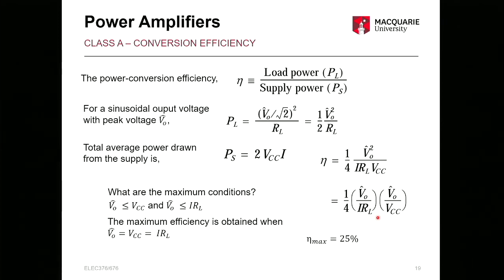You remember back to the waveforms, we knew it looked great because it does the 360 conduction angle, but it's not very efficient. And it uses a lot of power when it's at the quiescent state, the 0 input. So that means 75% of the power is heating up the transistors.